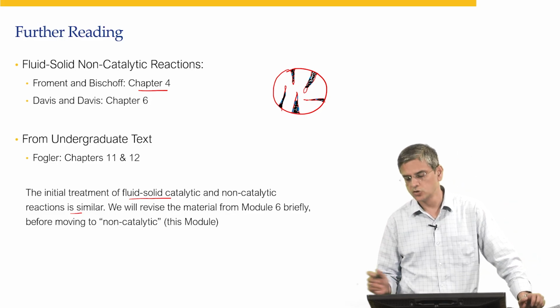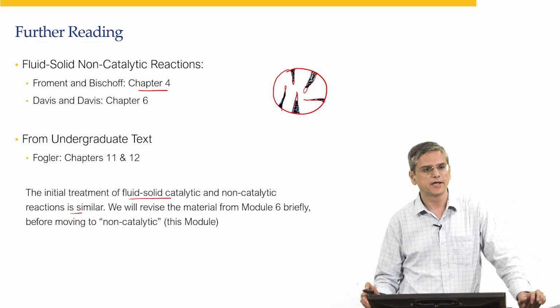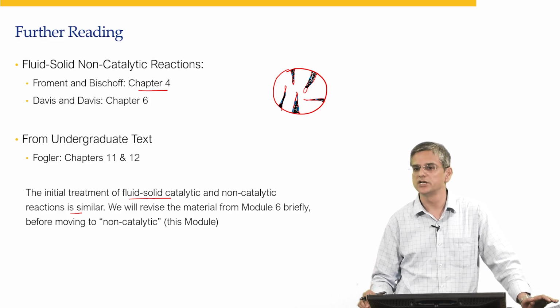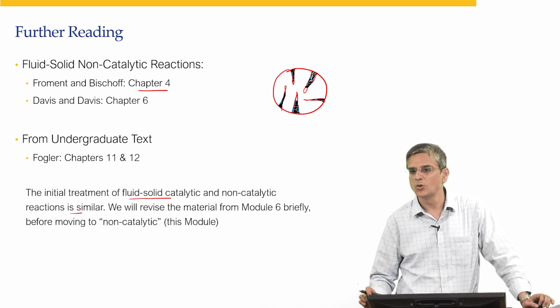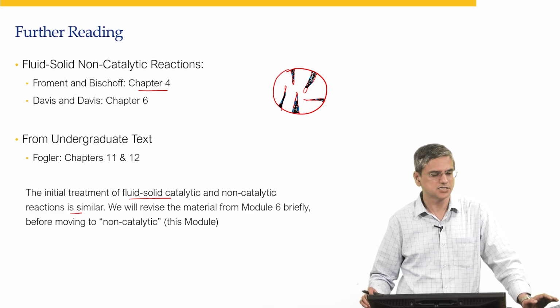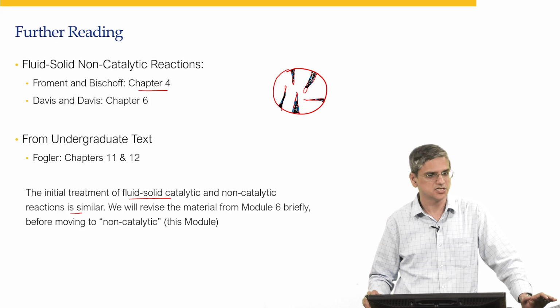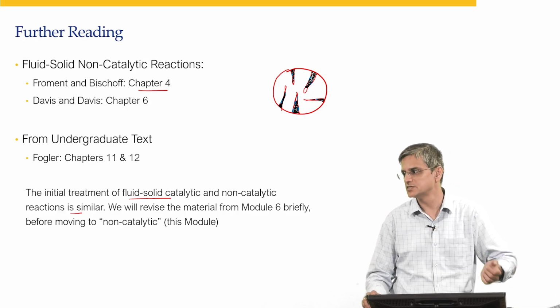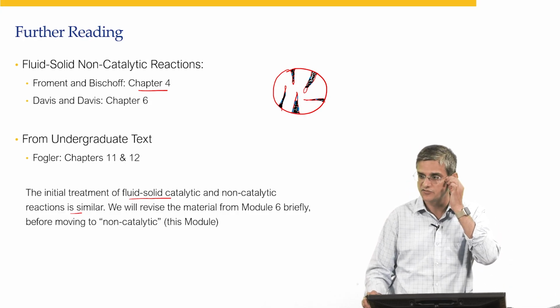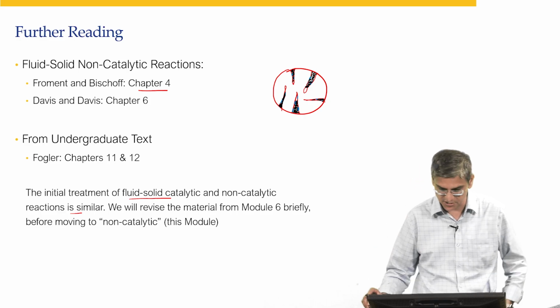And let's say now we are burning off that coke using oxygen, right? So when it comes to the gas phase, the reaction proceeds more or less in a similar manner, just how we analyzed the system in the previous module, because there's diffusion that is going to take place, there's reaction going to take place. So there's external diffusion, there might be internal diffusion plus reaction taking place.